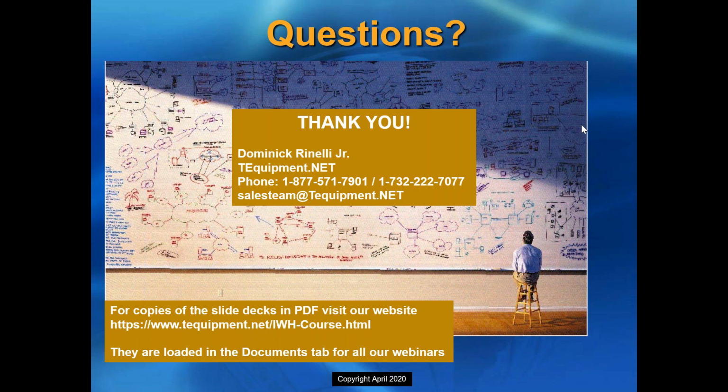because it tends to be a bigger deal to the plants and the organizations that have massive amounts of assets that would need enterprise software. They're actually able to do reverse engineering by doing an ad hoc calibration with the 754. And when it connects and doesn't recognize that asset serial number and tag, it asks you if you would like to create a new asset. So instead of having to type it out into the database first and download it, you're able to create the asset in the database as you're importing test results you've already created.